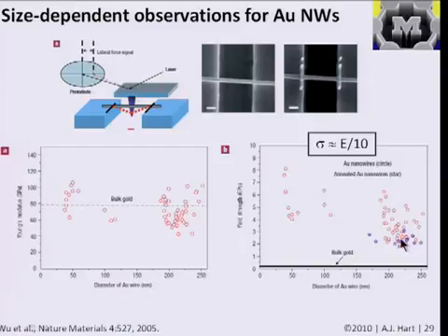And they found that the yield strength for all the sizes they studied was much higher than the bulk limit. And also, as the wires got smaller, the spread of strength values got larger, but the average strength went up. And this relates to the case of having fewer defects in the material and fewer flaws. They can be missing atoms, they can be vacancies, or they can be dislocations. Basically, the grain structure is changing as you go down to these small volumes. And this behavior will depend on the material you test.